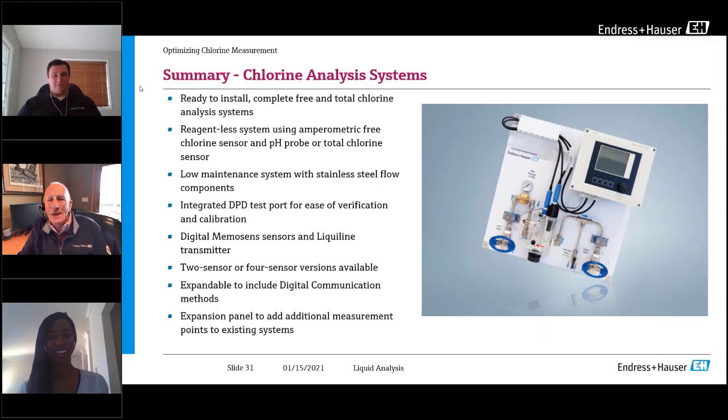Go ahead. Okay. Groundwater supplier 1 is making chloramines. Supplier 2 gets water from supplier 1. Supplier 2 needs to boost the chlorine before sending out. Should supplier 2 measure free or total before boost?